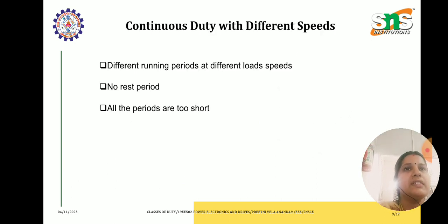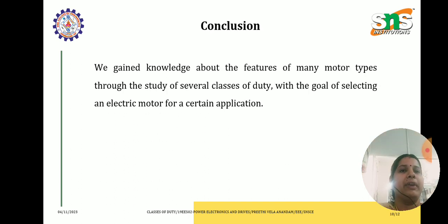The next one is continuous duty with different speeds. In this type of motor duty, there are different running periods at different loads and speeds, but there is no rest period and all the periods are too short to attain the steady state temperatures.